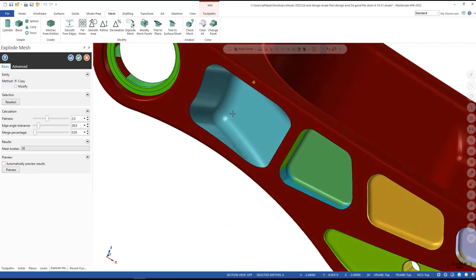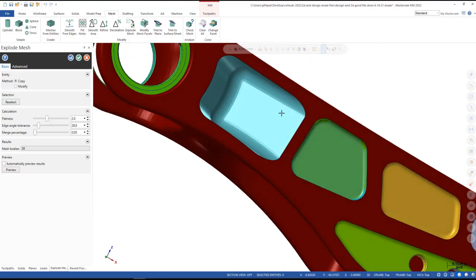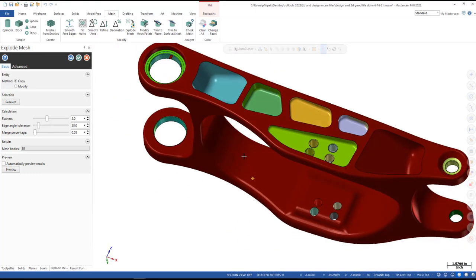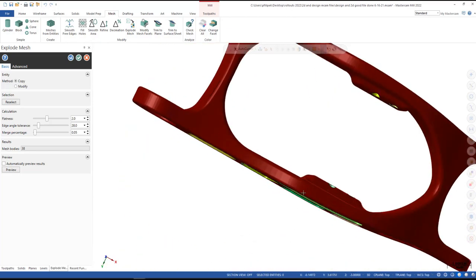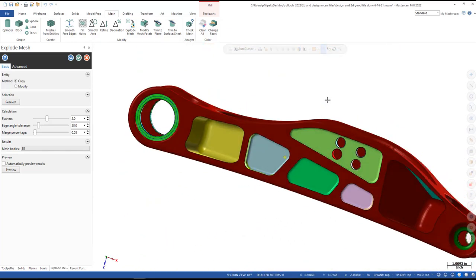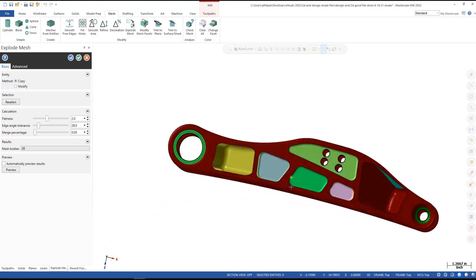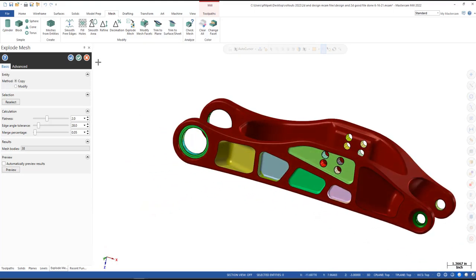I can see blue. So now maybe I could come into this blue pocket and I could select out of colors on the masking on the right. So I could come in here, and now there's going to be a bunch of colors on the screen potentially when I go to toolpath that, which can be kind of nice, and it helps me visualize what I actually have on the part, and everything is a different color. So quite handy for programming and working with a mesh file.